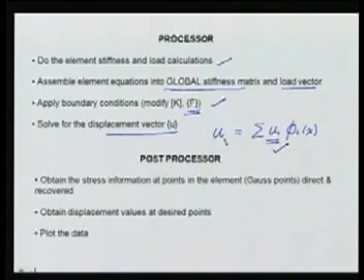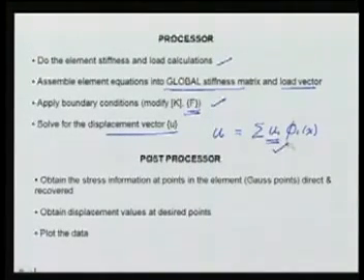Now, we don't have to do this per se. How will we do it? We will say, okay, which element do I want the information in. In the element, I know only the element shape functions are the active phi's, all the other phi's are 0. So, we will take those element shape functions, multiply by the suitable coefficients u_i, and we get u in the element. Take derivatives, and we will get the derivatives of u in the element.